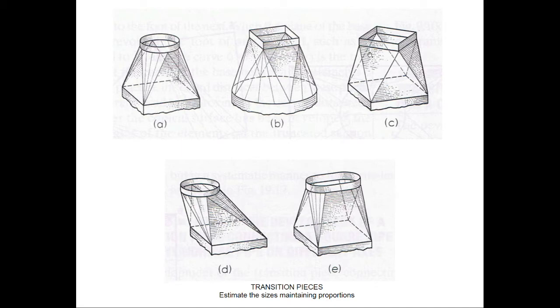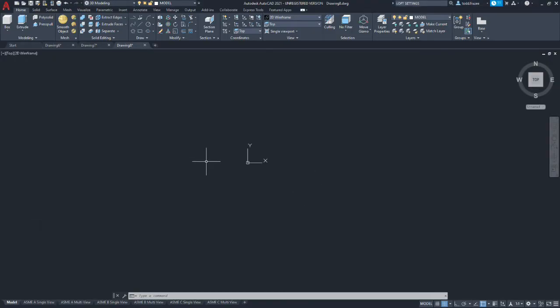It's hard to say, but it looks like perhaps the width of the larger square is the same dimension as a measurement from corner to corner. So we need to draw the first rectangle to derive the hypotenuse of a bisected triangle there, so that we know what size to make the other square for C. So let's go to AutoCAD and put it to work so we don't have to do math.